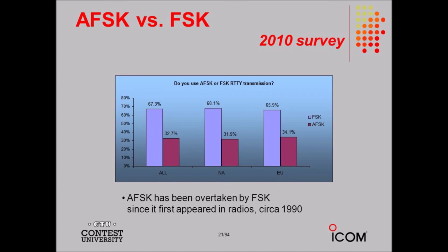When we employ phase modulation, PM, we must process the audio signal before we apply it to the modulator, adjusting the frequency response of the audio amplifiers. Otherwise, the signal will sound muffled when we listen to it in a receiver designed for ordinary FM.